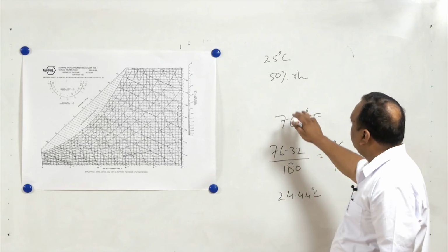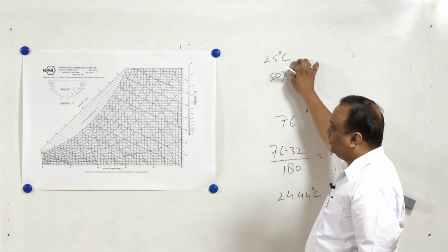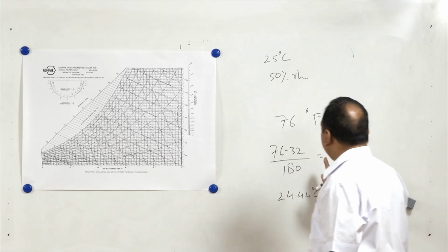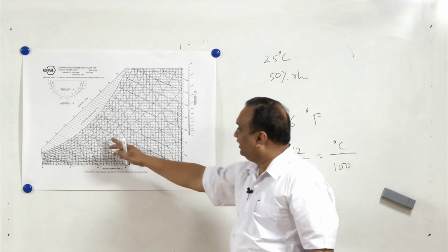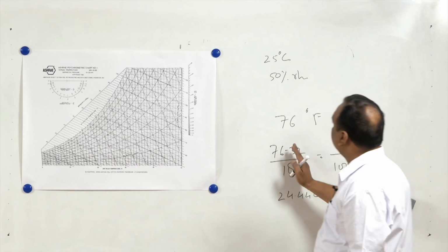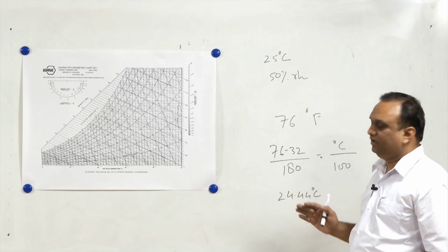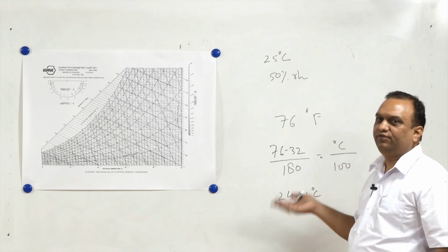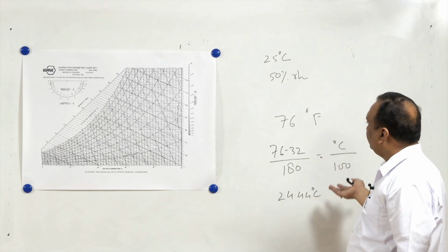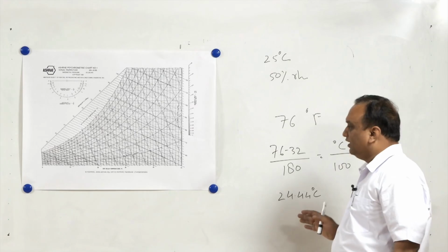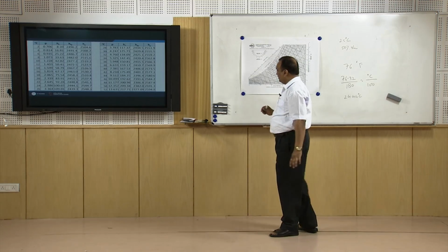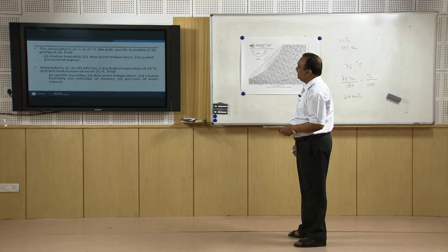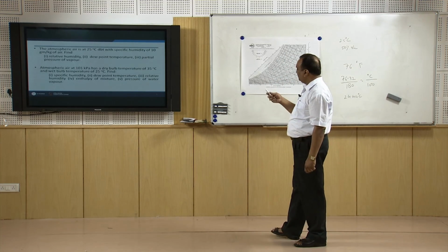but we take 25 degrees centigrade because in India most of the time we are doing cooling. So we do not recommend cooling up to 24 degrees centigrade. We say if you cool up to 25 degrees centigrade, the ideal state is attained. This can save some energy also, and at 25 degrees centigrade, most of the people in our country feel comfortable. Now after this we will take some examples. I think that will make things clearer.